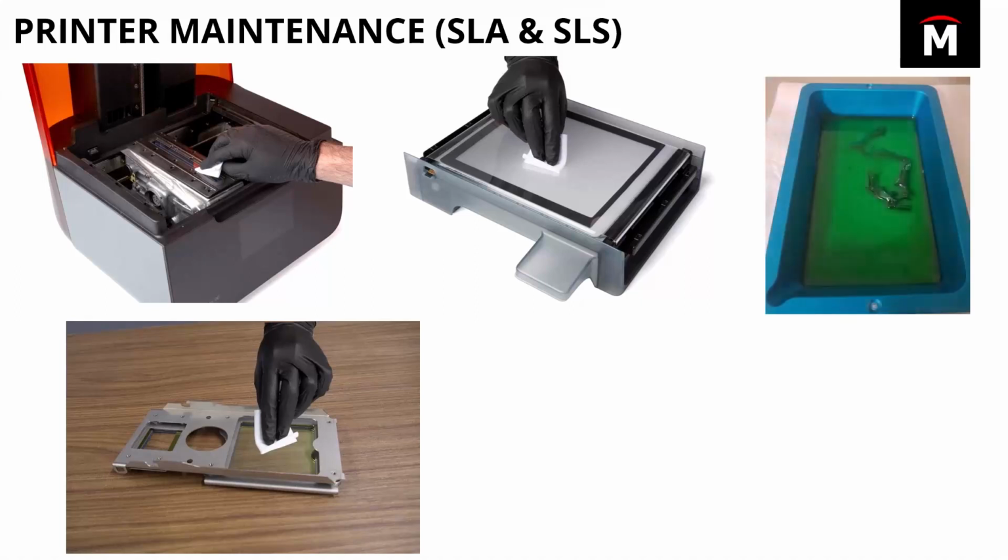Speaking of occlusion, you want to make sure you do not have any cured resin in your vat of uncured resin. So this is definitely a bad situation. You want to make sure that's cleaned out, because again, it's an obstacle between the laser and your actual part.